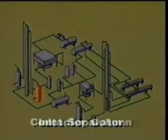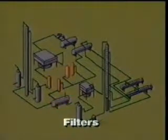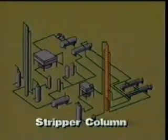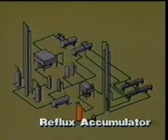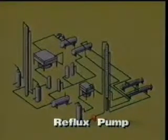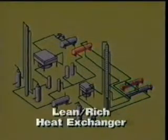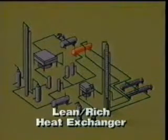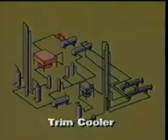Typically, the amine sweetening unit is made up of the following components: the inlet separator, contactor column, outlet separator, flash tank, filters, stripper column, reflux condenser, reflux accumulator, reflux pump, reboiler, reclaimer, lean rich heat exchanger, surge tank, circulation pump, and trim cooler.